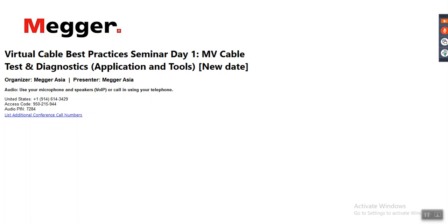And another question from Fajar: on tan delta, will the length of the cable affect the result? The answer is the length of the cable will affect your test load capacity. The base recommendation is 1 microfarad, about 4 kilometers. So, additional information for you all: if you are testing 10 or 20 kilometer cables using tan delta, that's again a big challenge. You need a very high capacitance tester to test tan delta. Again, dielectric analysis will give you a very confusing result because the cable is too long.